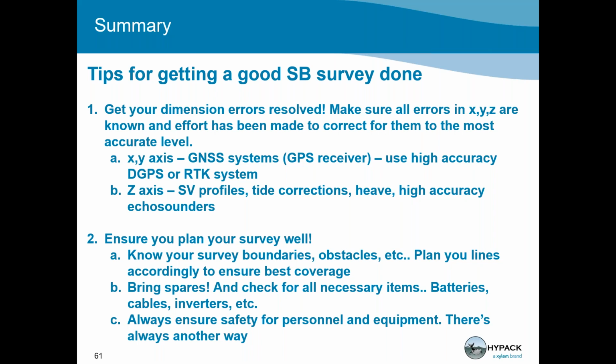If you want to measure the thickness of the sediment, I recommend, though, maybe not using an echo sounder, but rather a sub-bottom profiler that brings you deeper into the sediment thickness. But yeah, you can run lots of equipment at the same time. That's no problem. That's the beauty of HYPACK. I know people that run an echo sounder, multi-beam, side scan sonar, a magnetometer, and sub-bottom profiler at the same time, and collect everything in one software, which is called HYPACK.